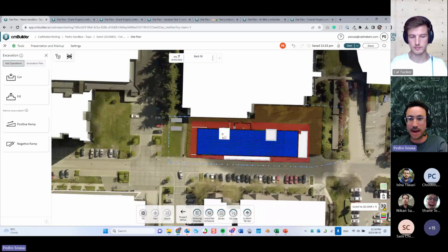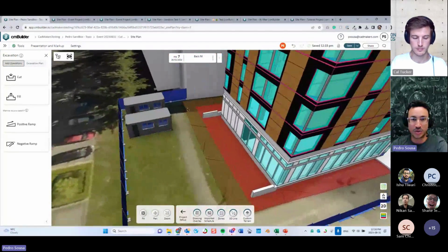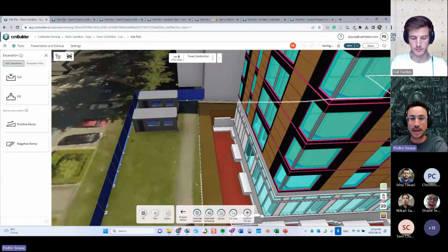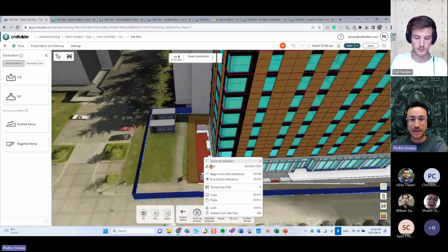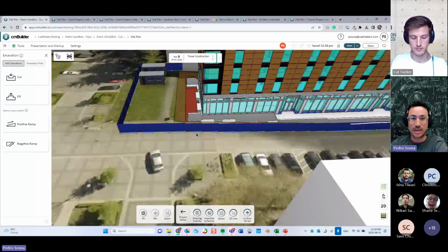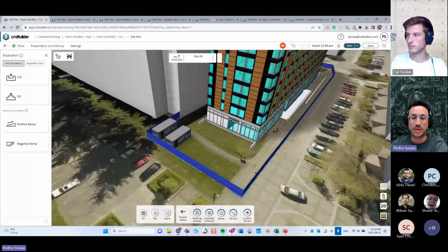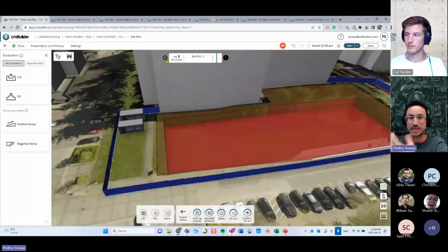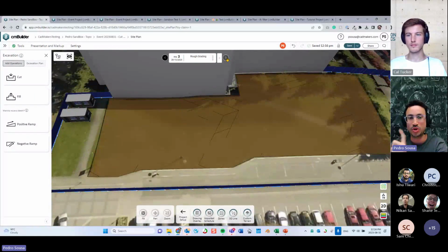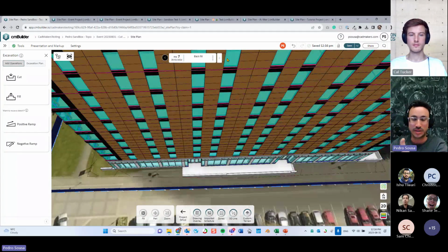But when I go to the backfill stage, you see that I can see all the zones. So before I get to my backfill stage, I'm going to select the zones and end them on the milestones, right? So let's end the zone in here, and let's end this zone in here. So when I go to the next stage, the backfill brings you back to your original stage. So basically, because the excavation colors are taking whatever is projected on the map, you can control which colors each of these operations will have at different points in time.